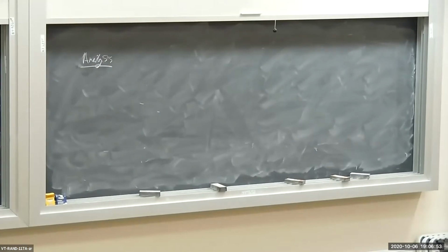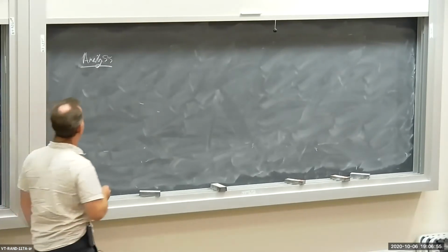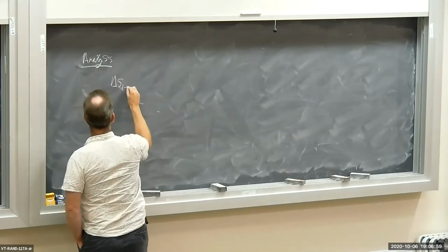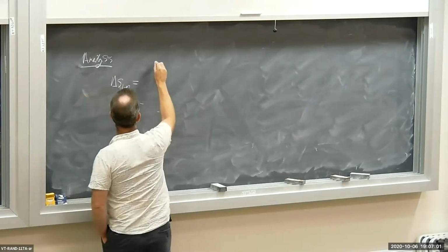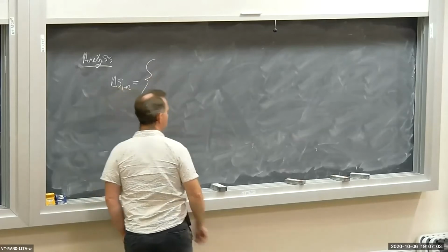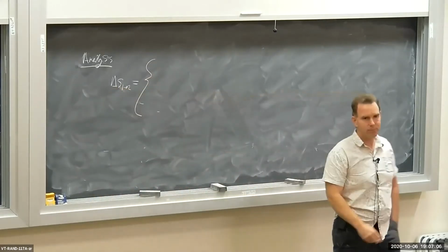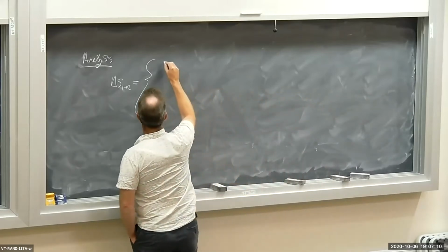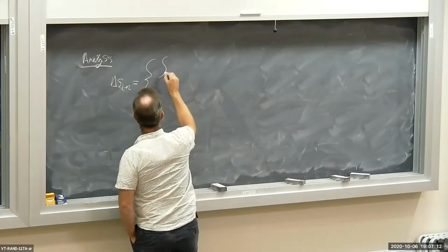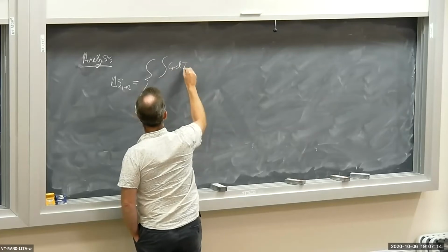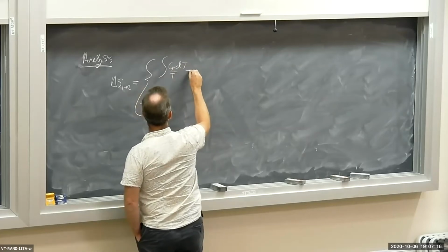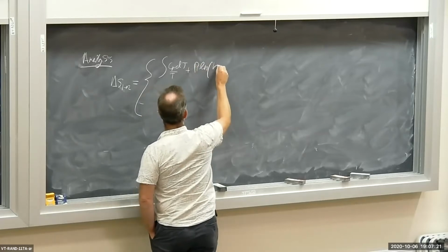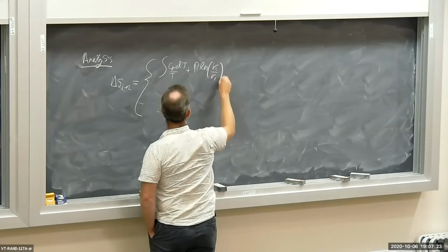Okay, let's write the equation for delta S for an ideal gas. So delta S, this is specific entropy change. And then I've got two versions for variable specific heat. I've got the general one, integral of CV dT over T plus R ln V2 over V1. I have that.